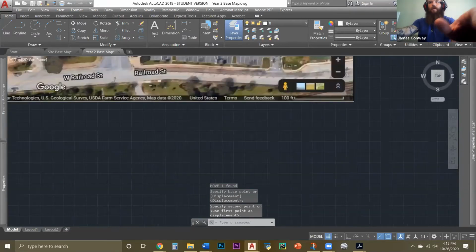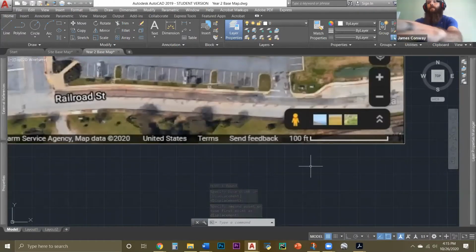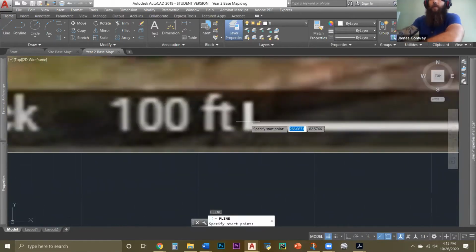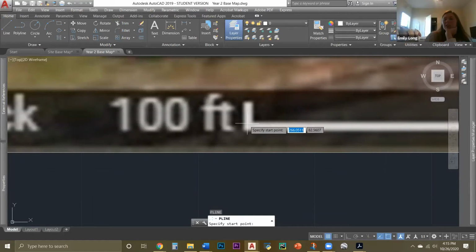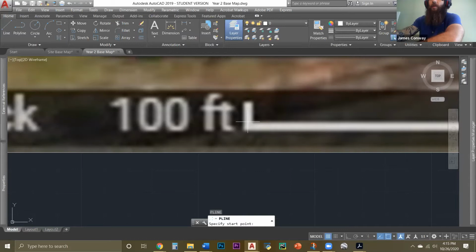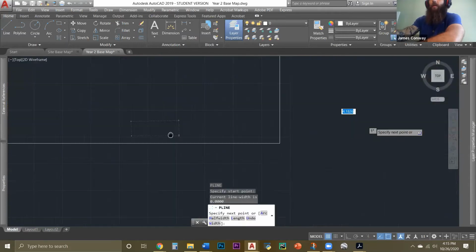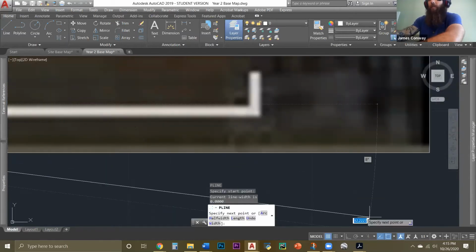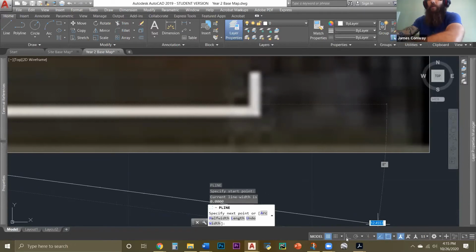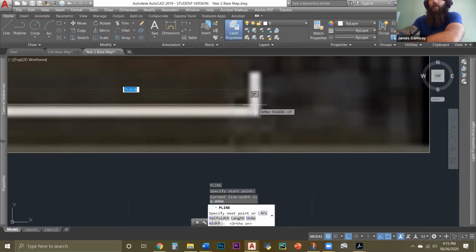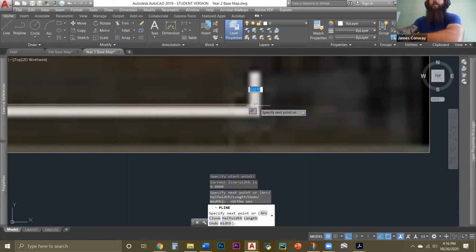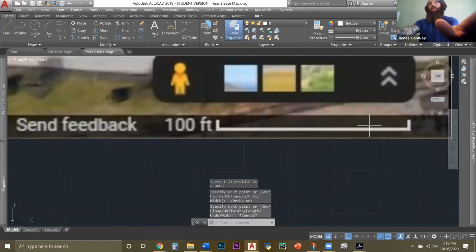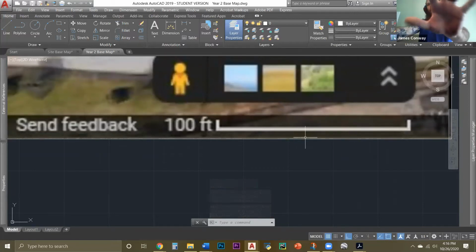All right. So now we go PL, enter. I like to zoom in and get right in the center. PL is how you can draw a line; you can either do PL or L. Yeah, I always use PL. It's a habit. I like to go in the center of these little upshoots, because you've got to go somewhere, I guess. So, all right. Now we know we have a line that is the same length as that line, but we don't really know how long that line is.